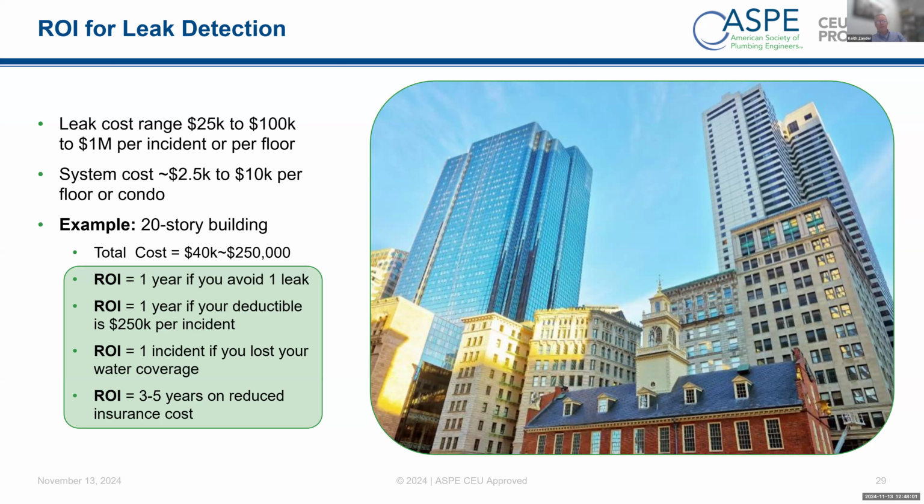So all these questions you have to ask the customer. What's your deductible? How many leaks have you had? How many different fixtures do you have? What does your risk look like on the project? How old is the piping? Do you know where all the piping is? Do you know where all the valves are? Do you test your valves?